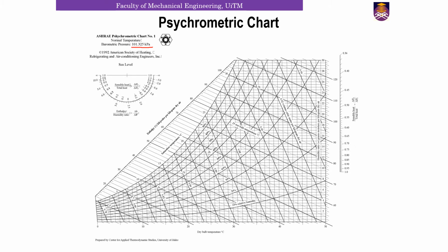As you can see from here, you have the psychrometric chart shown as what we've discussed earlier in a shoe form. All right, so on the y-axis here, you have all the values for humidity ratio. This humidity ratio, bear in mind, the unit is in grams moisture per kilogram dry air. We mostly use values in kilograms moisture per kilogram dry air, but in this chart the value for humidity ratio is given as grams moisture per kilogram dry air. So if you read 22, the value is 22 grams moisture per kilogram dry air. You will need to convert this into kilogram moisture per kilogram dry air for your further calculations. So that is the value that you have on your y-axis here.